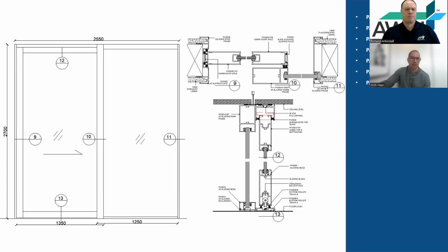And then the track components, which is the top track, which guides the door along the top here, half a length. Half a length of, we've got 2-piece bottom track in this design, so we need half a length of both of those. Now, just a little side note, our track is actually 5.1 meters, so that's why I've allowed for it to be 2,550 for this example. If the overall length was, say, 2.7 or 3 meters for this opening, then I would normally just allow for a full length of track, and the offcut is obviously going to be wastage unless you've got some smaller sliders somewhere.